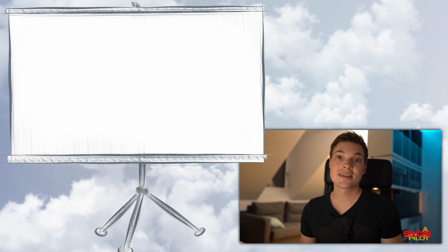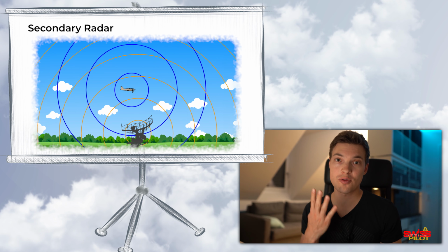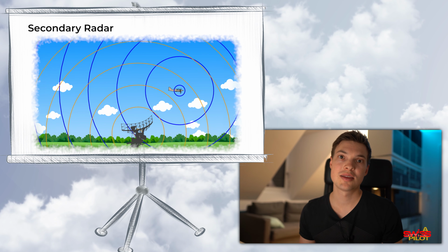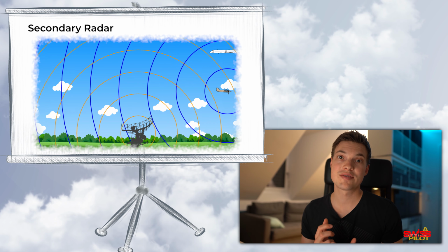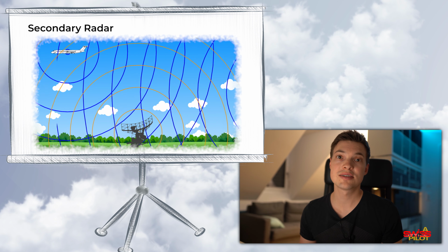Now, with secondary surveillance radar, transponders started to send replies to the ground station's interrogations, first using only the classical 4-digit code that we all know. That was only mode A. Thereafter mode C was invented, where the replies also contained the aircraft's altitude.